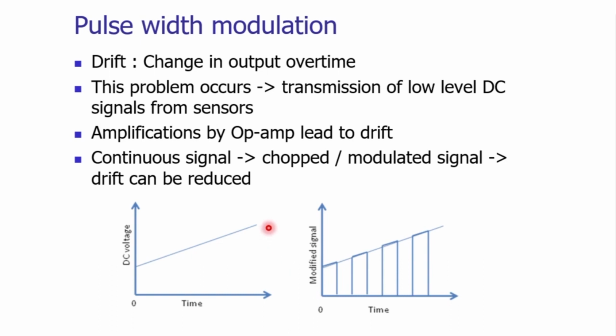So if we program the microprocessor based on the drift itself, if we give any tolerance value to the drift, say the drift should not be plus or minus this percentage, then the microprocessor will understand that and it will take the decision appropriately. If we are instructing the microprocessor that the constant value is expected, say x, and the drift is allowed only about 5%, but here in this case the drift is more than 5%, that is around 20 to 30%.